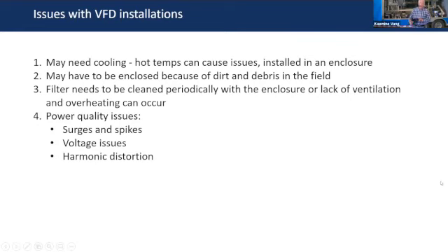There are issues, especially in California, but I imagine in a lot of places, it gets pretty hot out in the field. And so you have to have an enclosure, and you've got to run maybe an air conditioning unit or something like that, especially with bigger horsepower VFDs. Some of the new VFDs can handle up to 150 degrees. So if you encase them with a fan and stuff, they'll be pretty good. But a lot of times they'll be even better if you do enclose them and cool them. The problem is, it costs money to cool them. And so that's working against your energy savings, the fact that you're running the pump slower. Maybe because the whole system has a lot of dirt and debris and dust in the field.